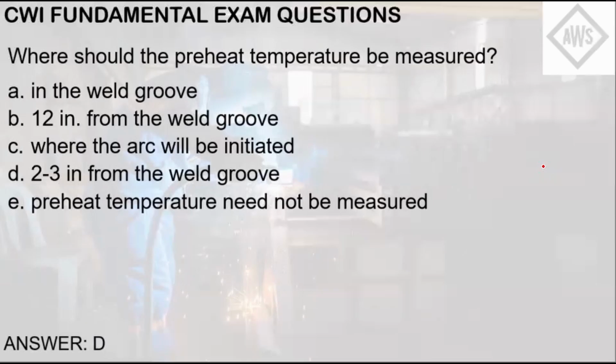This is because this is where the HAZ, or heat affected zone, is, wherein the highest susceptibility of martensite formation can happen. So what does that mean? HAZ refers to the portion of the base metal that has been heated to high temperature but not melted. When it cools off, the base metal undergoes a microstructural change that can affect its mechanical or material properties such as strength and toughness. Martensite formation can lead to brittleness of the base metal, which we don't want.